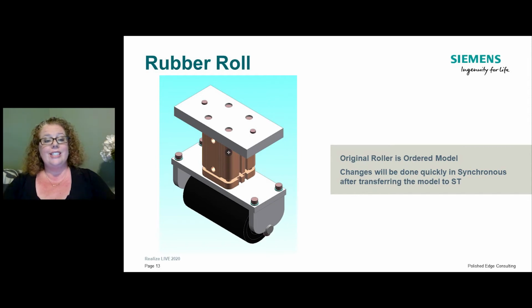The first few models done in sync can contain frustrations like the video showed, but after learning what dimensions to secure and which can change, designing in synchronous becomes effortless. The old adage, practice makes perfect, applies to both ordered and synchronous modeling. When your CAD library contains thousands of ordered models, moving to synchronous can be a daunting task. But as you saw here, a quick change to one of the traditionally ordered models gave us the advantage of a top-down change using synchronous technology.